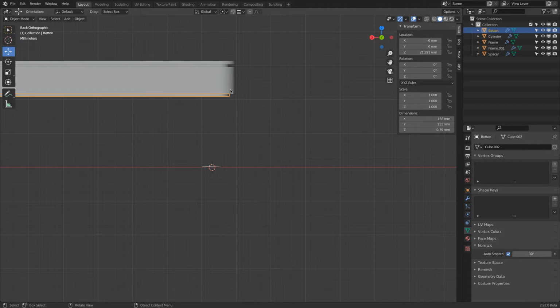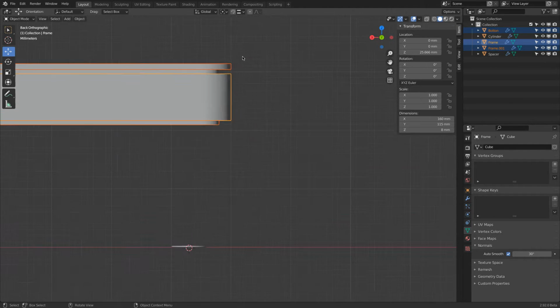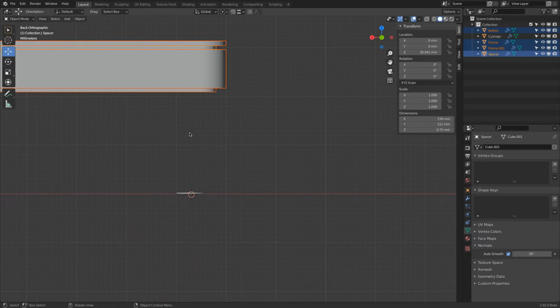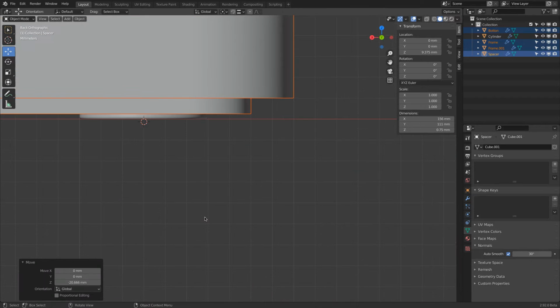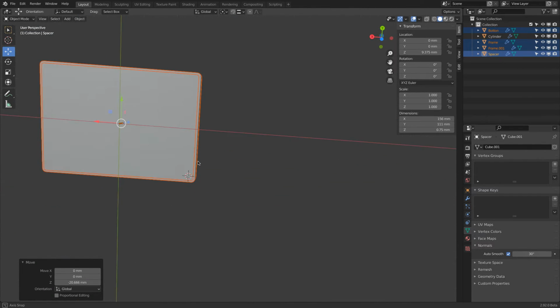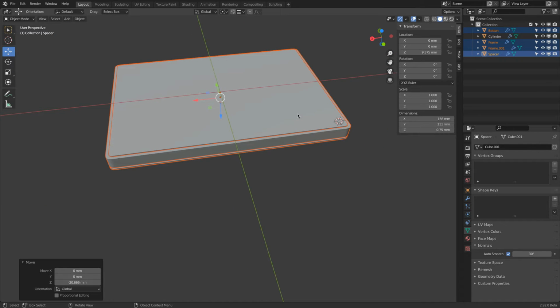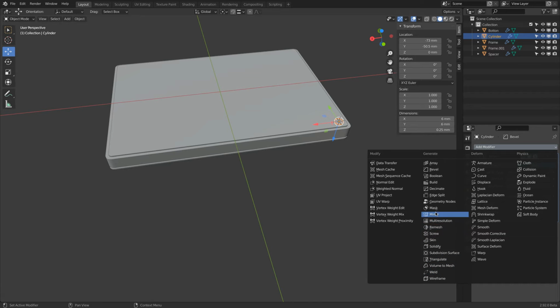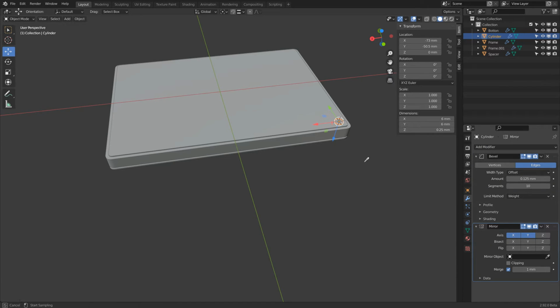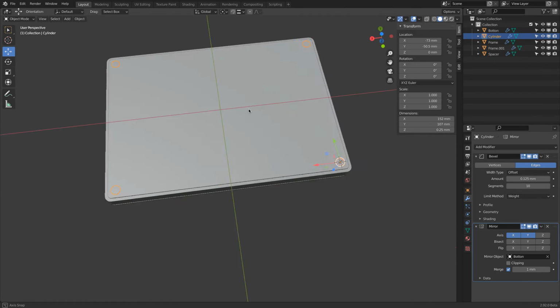I can select all my objects here, hopefully, there. Then GZ, move this down, hold the control key till it snaps to it. Pretty good. Okay, so it was one very easy way to position everything so it sits on the ground correctly. This I would like to mirror along X and Y for the bottom. You see also I can pick objects here in the outliner too. There we are.